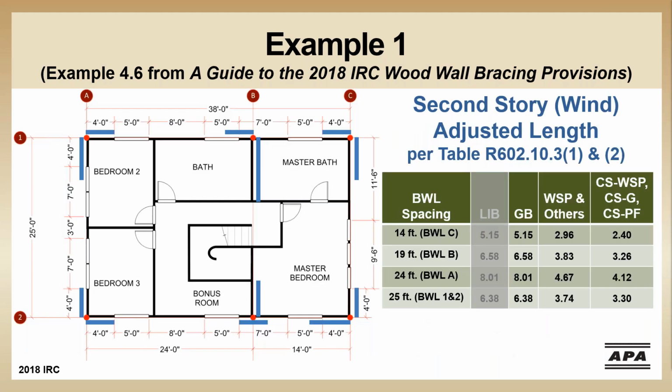So moving up to our top floor now, I've left the blue lines to show where the brace wall panels we placed below are located. Looking at our required length, we can see that the minimum placement requirements we just checked at the lower story are going to still govern the brace wall panel length at this story. You'll also notice that some of these lines overlap window openings in the story above. So that's in 3 places.